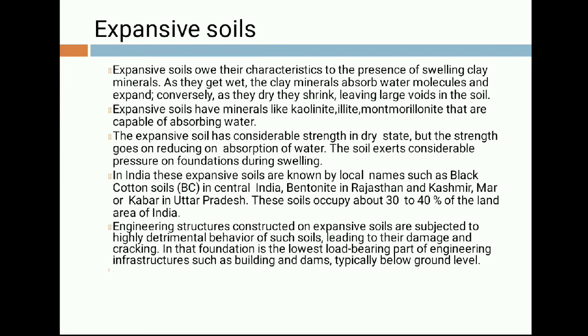Let's see what are expansive soil. Expansive soils owe their characteristics to the presence of swelling clay minerals. As they get wet, the clay minerals absorb water molecules and expand. Conversely, as they dry, they shrink, leaving large voids in the soil. That is, when the expansive soil is exposed to moisture, they behave in swelling condition, and when the amount of water is desiccated or evaporated from the soil, there is shrinkage in the soil.